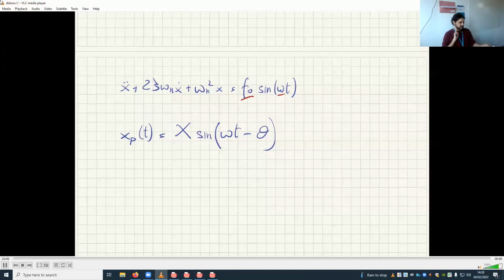So the force and the displacement will be out of phase. And at resonance, the force will be in quadrature. That means 90 degrees away. So it's exactly in between out of phase and in phase. And that is where you are pumping energy into the system continuously without even realizing it. And so the energy in the system keeps increasing and increasing and increasing, and then something breaks.